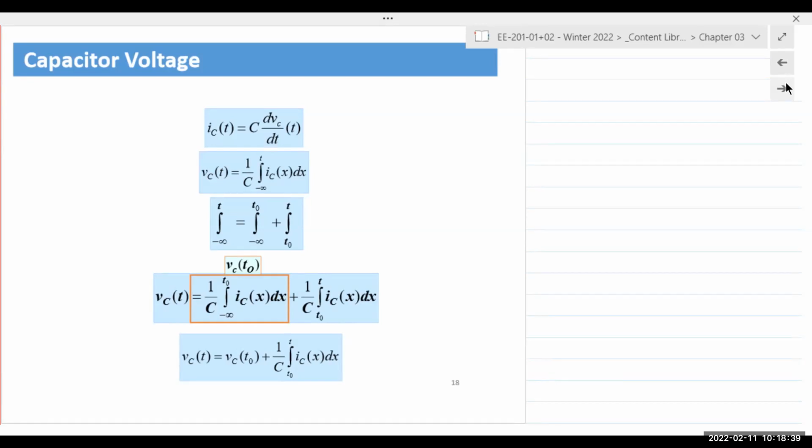The form of the VI equation, the form of the IV equation, the alternate equation is all exactly the same. If current is the derivative of the voltage, in order to find the voltage, we simply integrate the current and add up all the slices, right? You slice it up, dx, and you add up all the slices, you get the capacitor voltage VC. So you're not interested in the derivation as much as, well, students should understand what the equation represents, what it means, and what it is doing, and how to apply that equation.